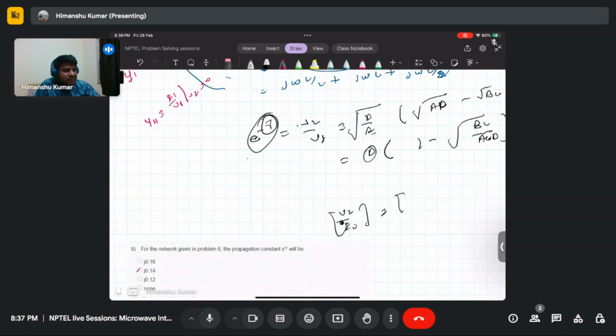You can derive it in terms of y or z parameters also. If you convert all these ABCD parameters into z parameters, then that will be the equation, and you can manage with z or y impedance only.